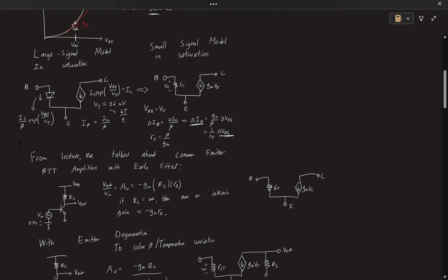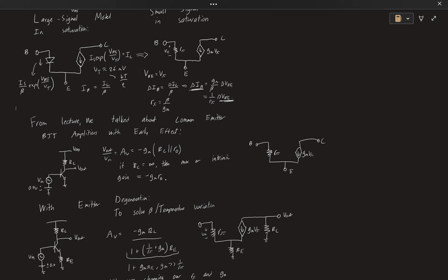So going back here, we know that our emitter is going to be grounded, right? Because we have this ground here, so we ground ourselves there. Okay. We know that this is going to be our V out, right? So what we can do is just replace this, call it V out, and now there's a few things here. We need to figure out what do we do with this RC and how do we approach this block here, right? So we know our V in is AC, purely AC, so we know that's going to stay.